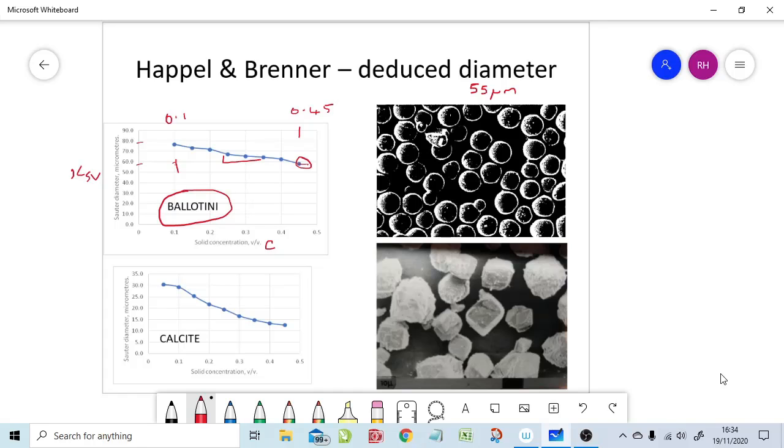Whereas really, if we had a value of Sauter mean diameter that was valid across all the ranges, and it gave the correct settling velocities, because these values here have all been deduced by rearranging the force balance and the Happel and Brenner equation combined. So they've been rearranged to work out what x is from u0, from the observed settling velocity in batch sedimentation. All these are experimental data. These data points are all experimentally measured data, and a lot of them are replicate tests.